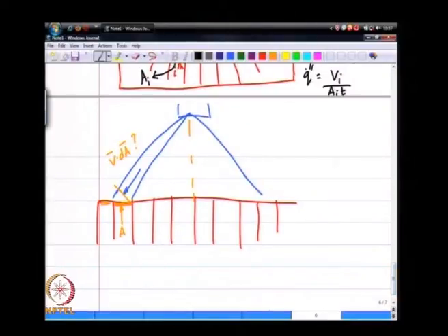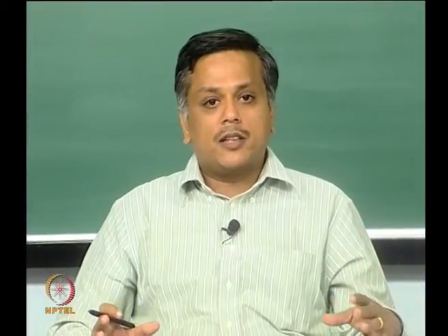And for what kind of sprays does this error become higher and higher? The wider the spray angle, you can see the angle between the velocity vector and the area vector increases, and the farther away I am from the spray origin, the angle also is likely to increase. So, if I am interested in patternation of large sprays, an inline patternator is a bad choice.